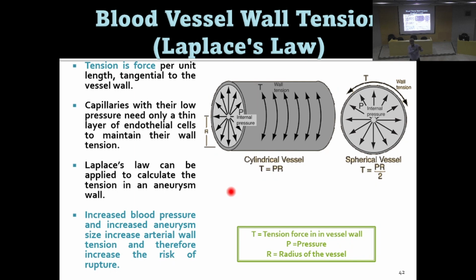When it becomes large, it means what? Radius is getting bigger. When radius is bigger, cross-sectional area is getting bigger. So velocity goes down according to the continuity principle. Remember, we say Q equals AV, isn't it? So cross-section and velocity are inversely proportional.